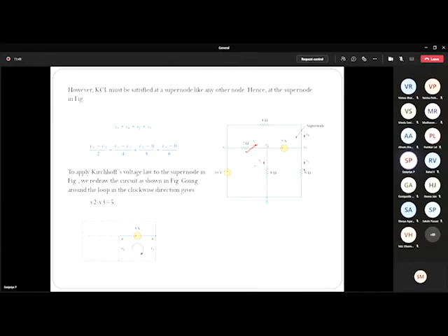So I'm going to write the equation and solve it. I can assume in any way. Okay, so I assume something like this. The entering current is I1, and here in this loop, the entering current is I4. So I1 plus I4 is equal to the leaving currents I2 and I3.